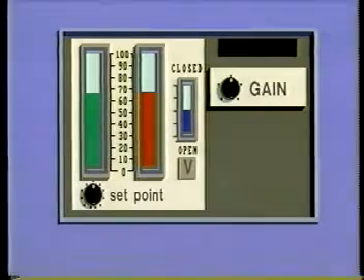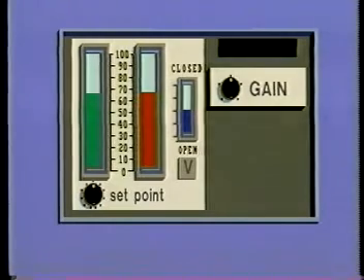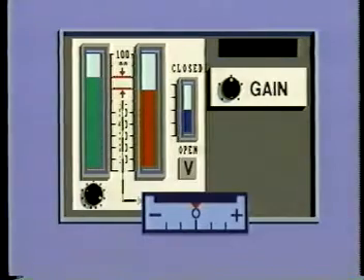Now let's look at the operating parts of the controller in the form of a block diagram. The measurement, in this case temperature, moves the red indicator. The set point, or green indicator, is adjusted manually to some desired setting, such as 80 degrees. Any difference between these values, as shown by the two indicators, is detected by a circuit controller known as the error detector, or comparator.